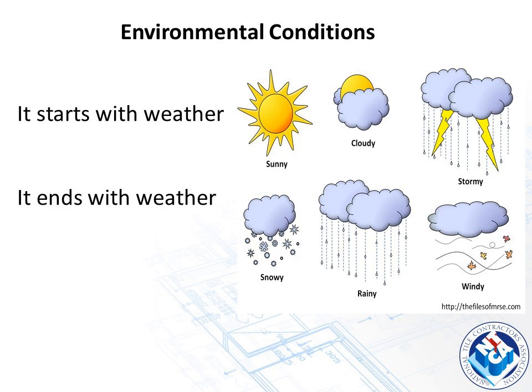And I'll use Colorado as an example. It's not uncommon to get up in the wintertime like this, and it's in the 50s as the day kind of warms up. That night it dropped down and snowed substantially during the night. Next day, wake up again. It starts to melt, gets in the 50s, 60s, 70s, and all that moisture starts melting through the tile deck, maybe into the mud bed. And again that night, it freezes again. Very, very difficult and demanding on a tile installation.